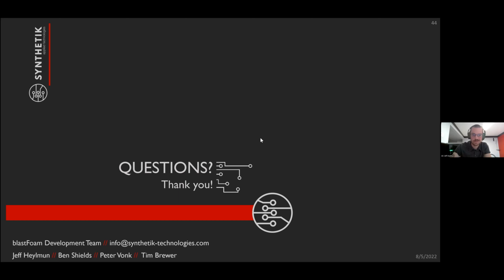Again, I haven't done a ton of investigation into that. CFL numbers, it's kind of just finding one that works. At the start of the simulations, you go from zero velocity and a relatively low speed of sound to basically a super high speed of sound. Once you get past that initial dumping of energy, it tends to be pretty stable.